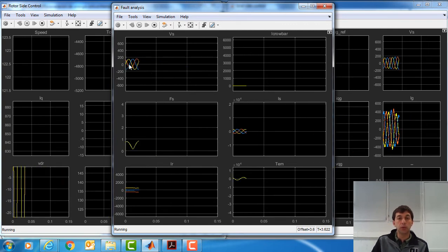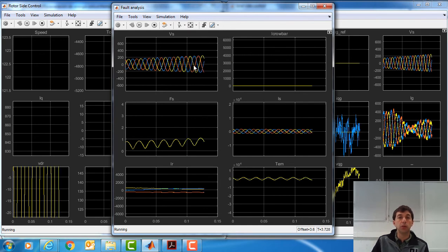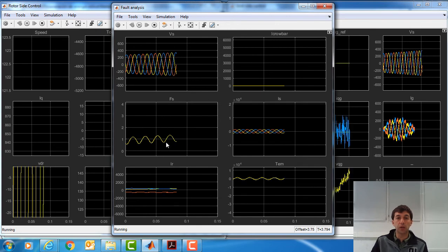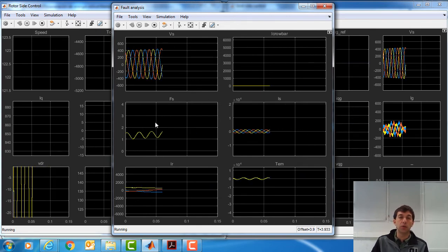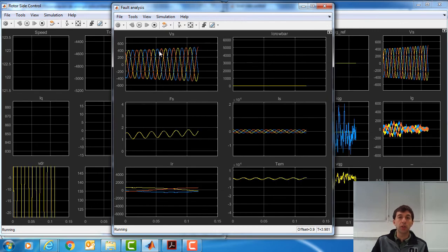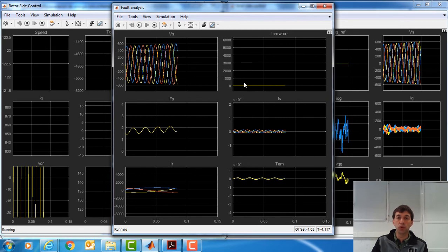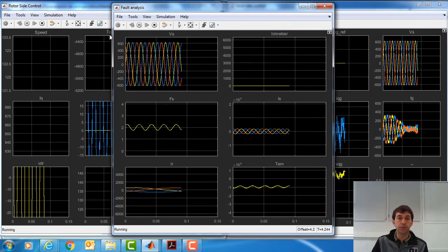And now the voltage recovery after the dip is happening, and therefore also we see how the stator flux is taking also its rated value according with the stator or grid voltage. During this time, obviously, the crowbar protection is not activated.